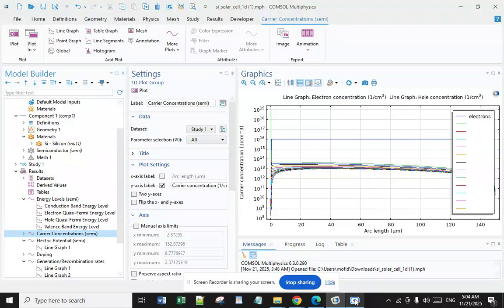For example, you can analyze the effect of different doping concentrations or geometries. The next is to refine the design. Based on the analysis, refine the design. For instance, if the simulation shows high leakage current, you may need to add isolation layers to the design.